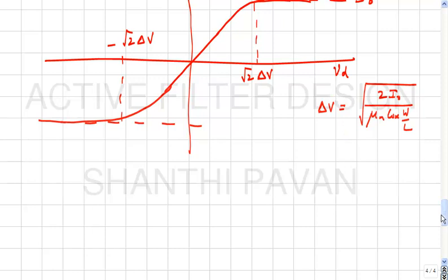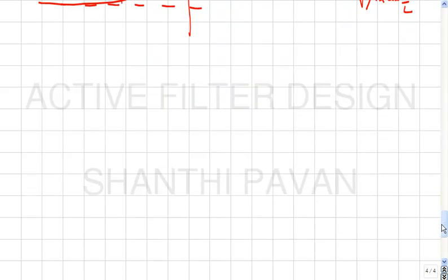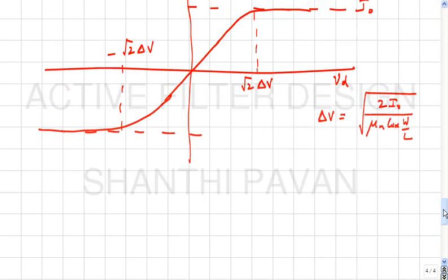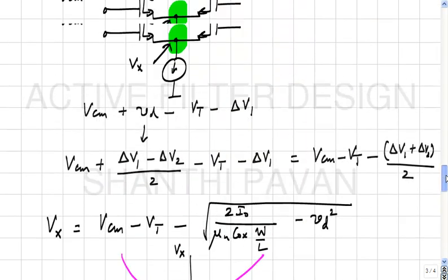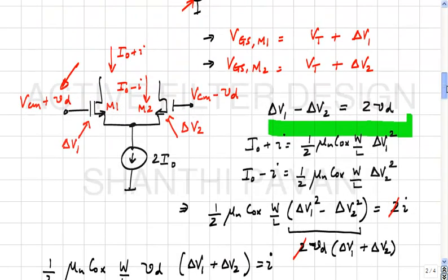This kind of analysis, in other words, this large signal analysis, or what happens to the output current when the input differential voltage is large, can be done for any transconductor. You understand? Okay. And therefore, all these calculations of linear range will depend on the specific transconductor that one is actually working with at that particular point in time. So let's look at other transconductors and see if we can do better than the differential pair. Since we are at it, we might as well also wind up on the differential pair, talking about some of its good things and bad things, right?